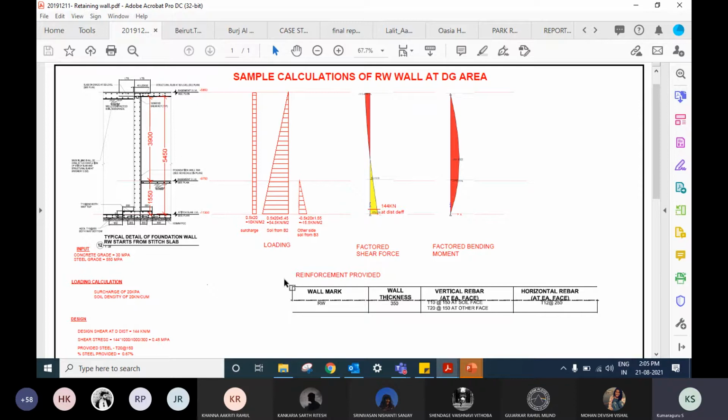So in order to find the bending moment for a simply supported member, a pin-pin connection, the formula is WL squared by 8. If you haven't written it down last time, please write it down right now and arrive at your numbers and see what happens. Now, in order to get WL squared by 8, we need the L and W. L is the spanning length, which is 6.4 meters in the current question. Now, how do we arrive at W?